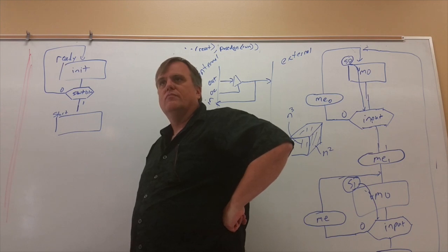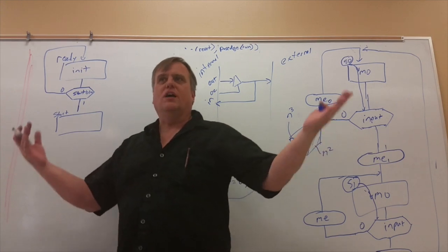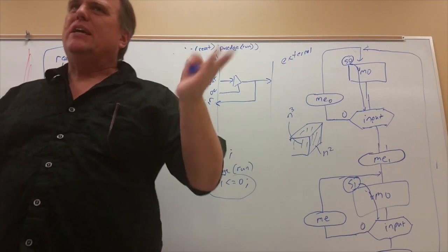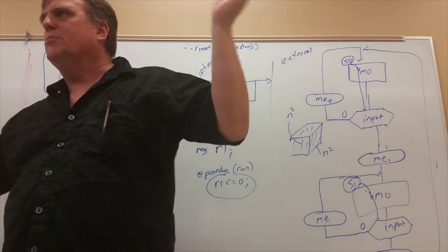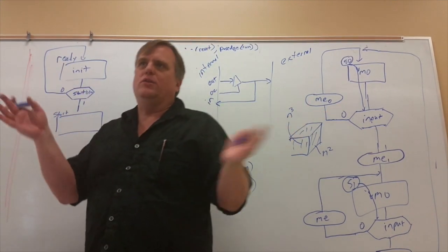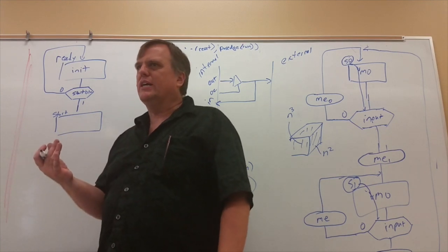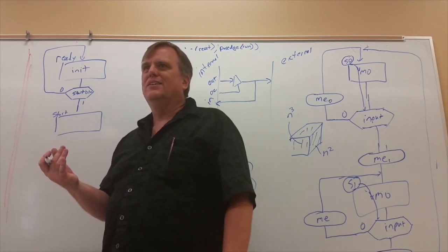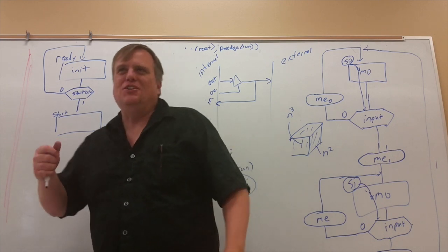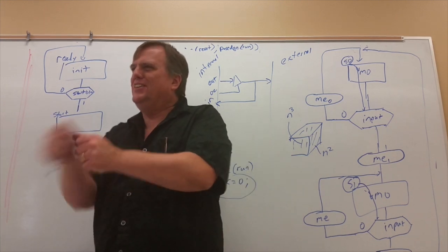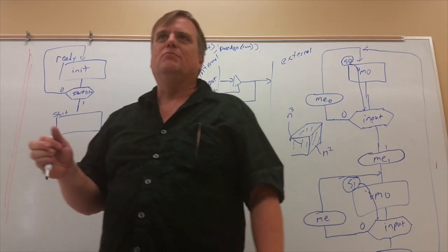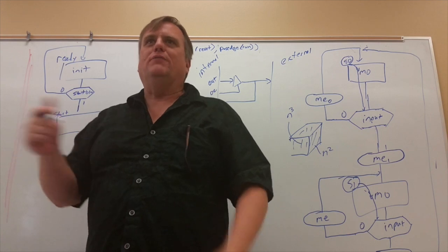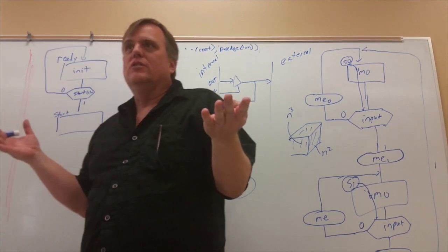You hit start and it waits some time. I forget the exact number they specified. I think it was like 2 to 10 seconds or something like that. It waits some random number of seconds. Why would it wait a random number of seconds? That way it's not the same every time, so the person can't predict it. You can't get used to timing the second you push the first button, so you're cheating and you don't have to wait for the light. So it forces you to wait for the light because it gives you a random time and you don't know what it is.